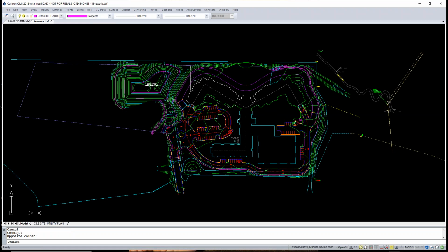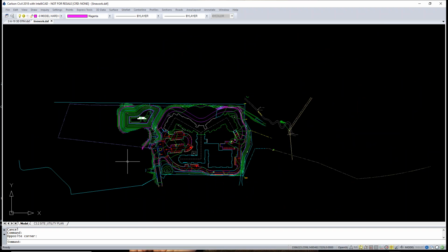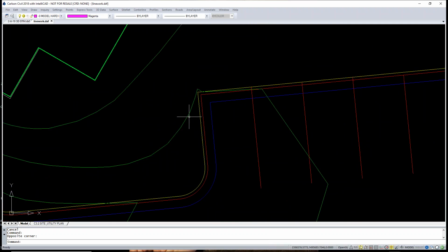Also on their line work file, this is good for their old 2012 redline stuff, like a redline GPS, because those collectors didn't have a lot of RAM, so it couldn't handle 3D line work and all. But their new tablets, they really need the lines joined up and all the lines 3D. So right now, probably only the contours are 3D. No, actually, those have been flattened, and all their lines are segmented. In the new system, they can click on one line and they can walk around the whole back of curve, and they'll give them cut, fill, offset the top back of curve, or anything else on the drawing.